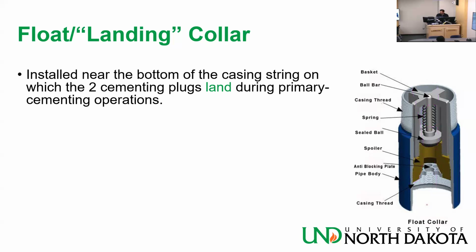Now, if you do your job right, as we said earlier, the bottom plug will touch here, right? And then all the cement will flow through the float collar, and the top plug will sit on top of that here. You understand? It's upside down.